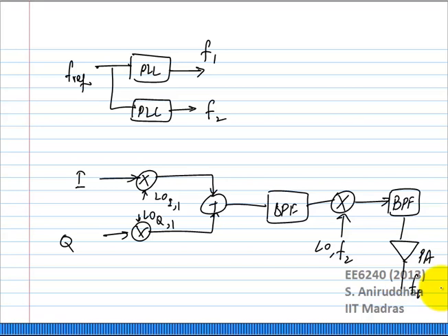Yes? Actually, in steady state there is no problem. Now, all I'm saying is, if your PLL is at the same frequency as the power amplifier, the coupling mechanism will be much stronger than if you actually have the PA working at a different frequency. Okay, this is a very practical case.